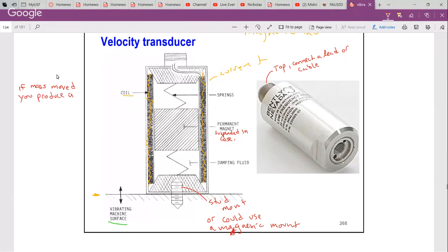Anybody into audio at all? Like if I say dynamic mic, what I'm talking about? Same principle as a dynamic mic. The only difference is instead of having a spring mount here, you actually have a diaphragm pushing on this thing. But you do have a chunk of inertia here, and that's why sometimes the dynamic mic is not as good as a condenser mic or something like that.